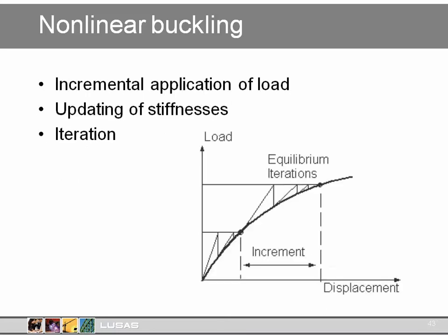The principle of nonlinear analysis using finite elements is that there is incremental application of load. The stiffness of the structure is not constant, as in the linear analysis, but modifies as the load is applied due to yielding, cracking, large deformations, lift-off and the like. So in a nonlinear analysis the stiffness is updated based on these things each time the load is incremented. Within each load increment, a linear prediction of the nonlinear response is initially made and subsequent iterative corrections are performed in order to restore equilibrium by the elimination of the residual or out of balance forces.